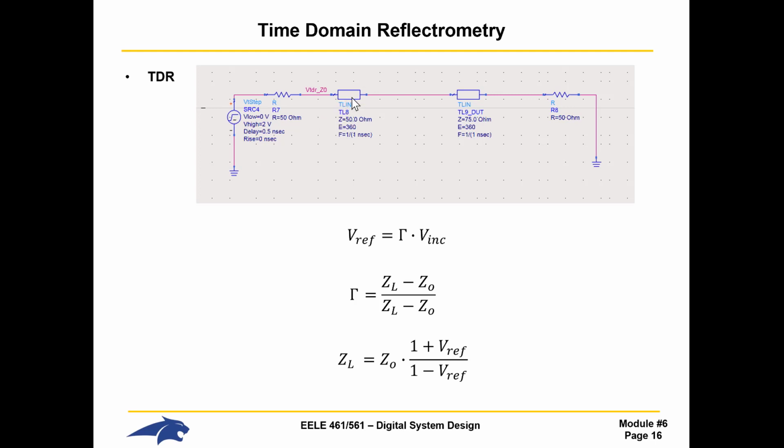I put the 50 ohm here because it's usually a cable. So you usually connect a cable to the oscilloscope or the TDR scope, and then you connect your DUT over here. But this is important because even if you don't have a cable on here, the source impedance of the TDR isn't exactly at the connector of the scope. It resides back a little bit. So even if you don't have this cable connected, there is a little bit of transmission line.